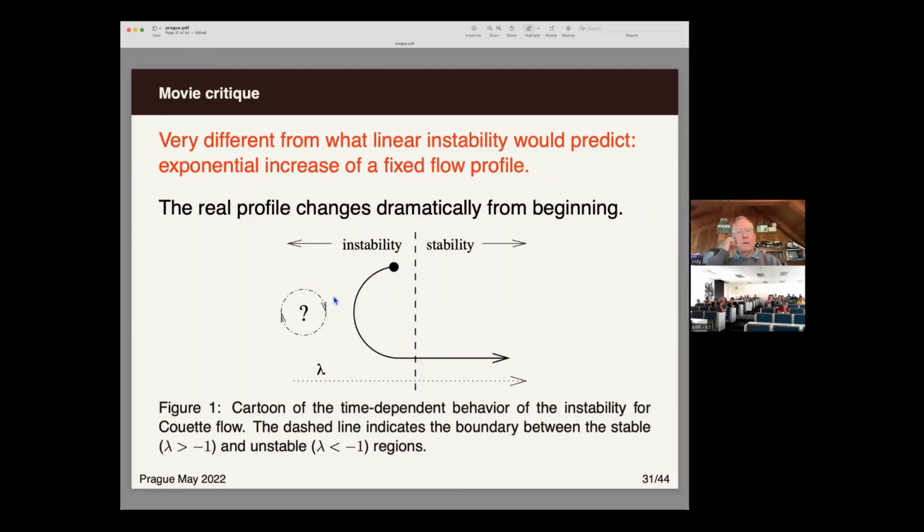So far, I haven't found it. I did think I had found it at one point for one of the large Reynolds number flows. And I was very excited because I thought it might involve a Nobel Prize, but then I realized that I needed to refine the mesh. So I refined the mesh and that went away. So in every case, all my instabilities eventually decayed. So we haven't found this persistent instability, but maybe there is one out there.